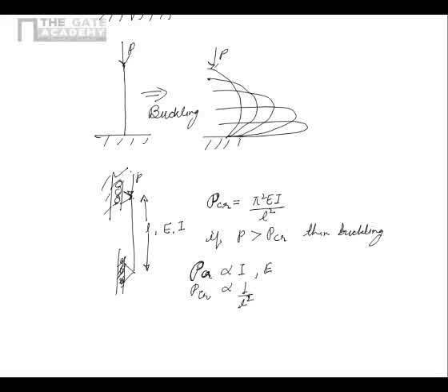So it's easy to buckle long structures or very high structures. So this is the kind of instability which sets in because of the inherent asymmetry in the structure and the inherent asymmetry in the loading pattern. And this is a very important thing to read, because